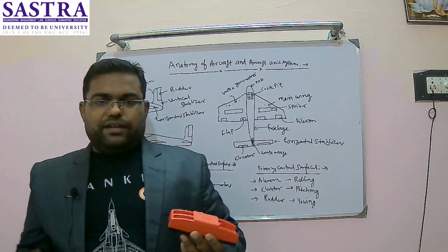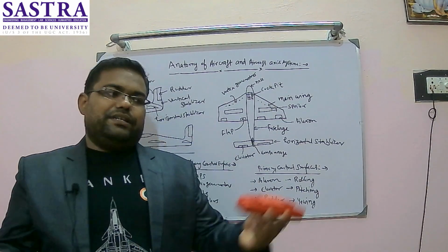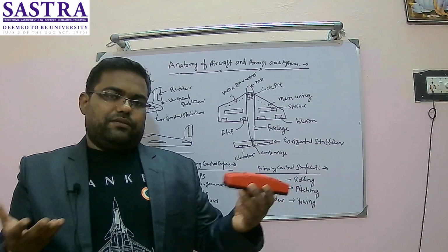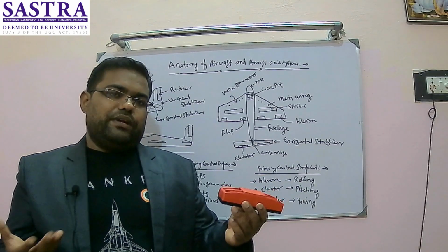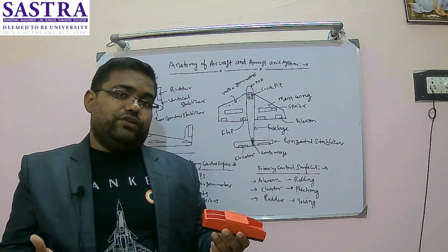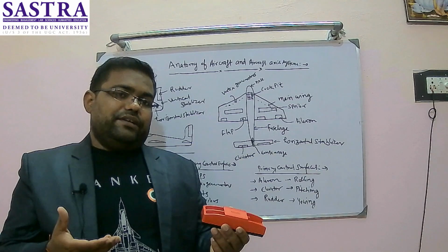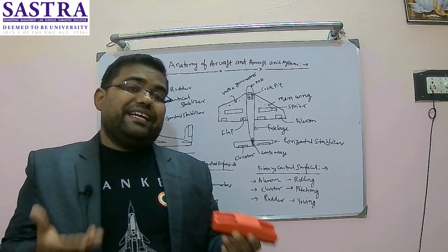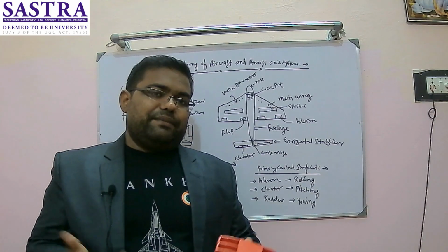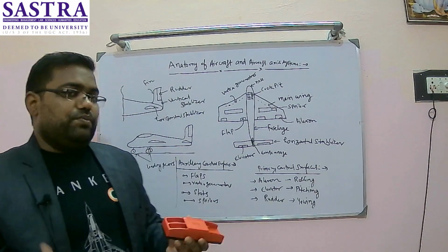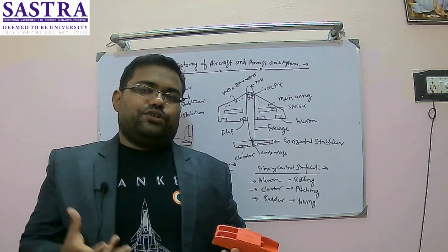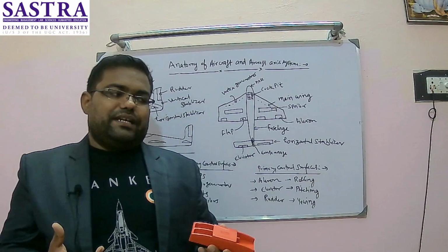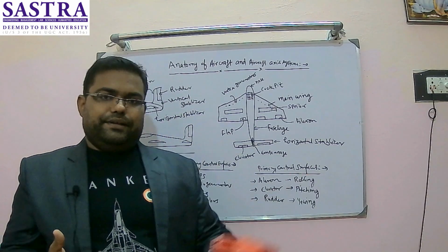So if I am deploying the flap, there will be a larger area of wake, because the wake area will be more. When the wake area is more, it is not going to help in the lift. That means it will increase resistance. So flaps can also provide braking effects. When we are landing, at that time you can deploy the flap to provide momentary braking action on the aircraft to stop the aircraft within a shorter landing run.